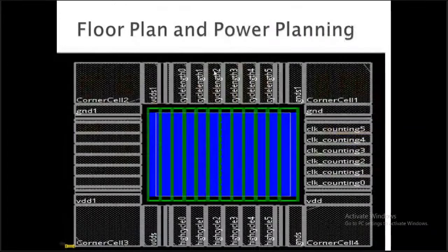If you see this circuit, this is completely a chip's inner look. This is the inner part which we call the core, and this is the outer part which we call the IO. The voltage level of the core is very low, you can say 0.8, 0.9 volt, and the IO voltage basically starts from 1.2, 1.8, 2.5, 3.3, and more based on the requirement.